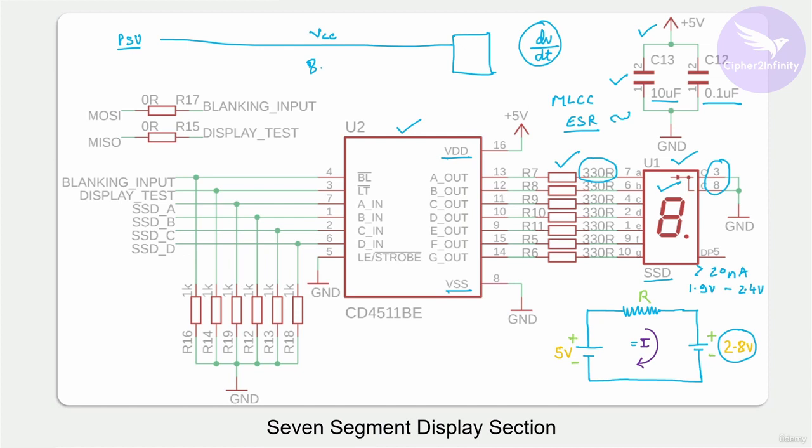If the distance is around 8 or 10 centimeter, it's completely fine; even if you don't connect this capacitor, the circuitry will still work. But if you are skeptical whether we should connect these capacitors or not, depending on the distance between the PSU and your IC, you can keep the provision of the capacitors on the PCB, and if you observe that without these capacitors the circuitry is working, then you can remove these two capacitors. So I hope that this point is now clear to you.